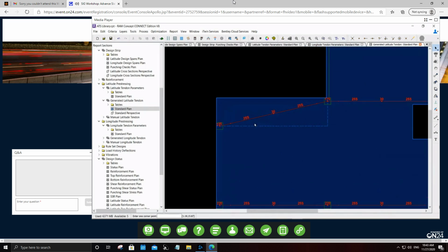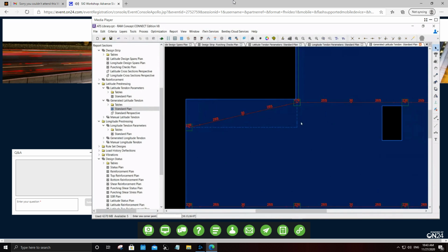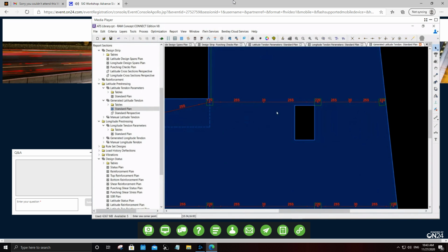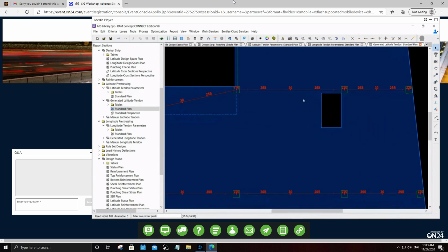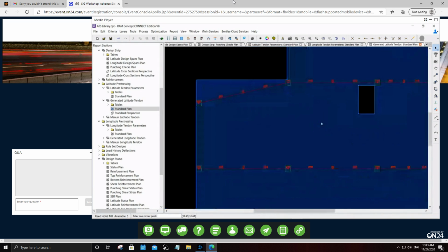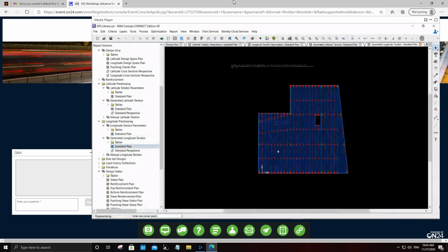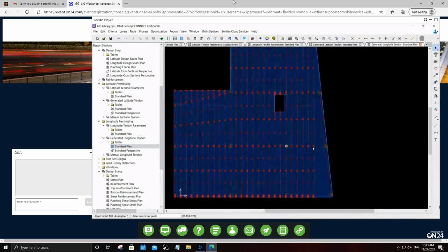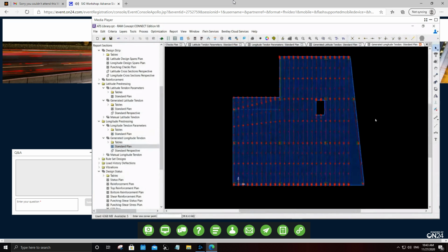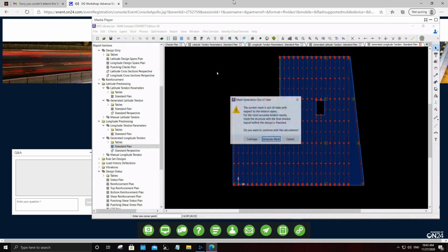So here you can see that these are the generated strands, and the digits which have been written here are in context with the bottom of the slab, that is the elevation of these tendons. So you can see the drapes going around. And let me tell you that I've just given the hint of where I need the tendons. These have been actually generated by the program. I have not drawn them manually.